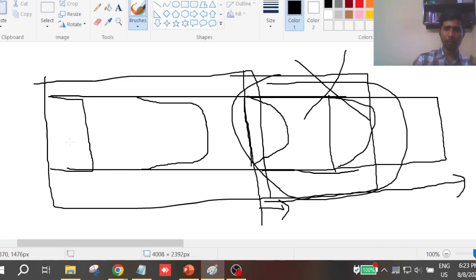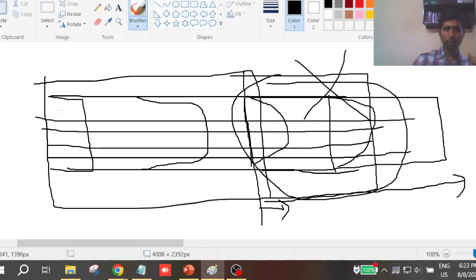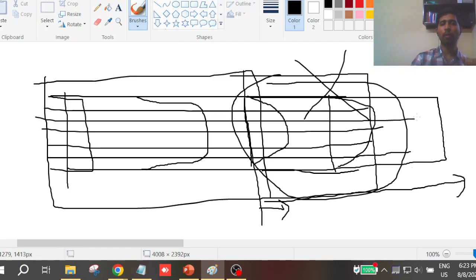That is the second step. You need to divide this whole domain into a small number of elements, which is called a grid, which you have already learnt in the week 2 contents. If I take a very long length, I will get more elements, which will increase my computational cost, the time required to solve the problem. So I have to take an optimal length. So I take that fully developed length.